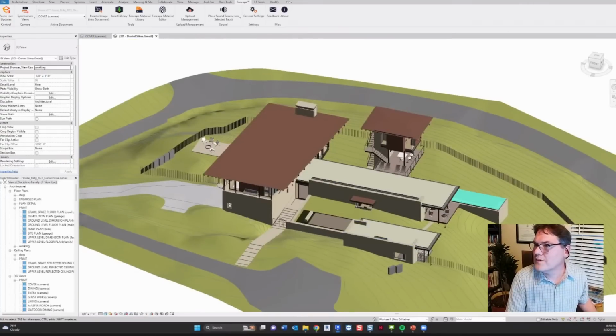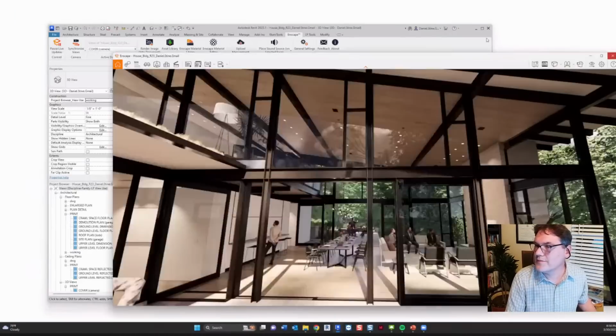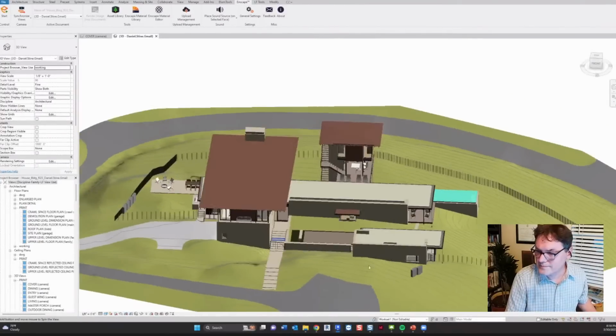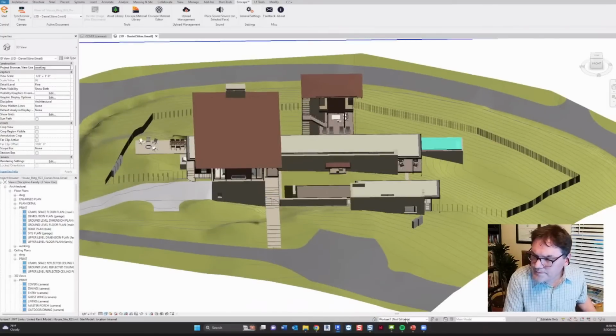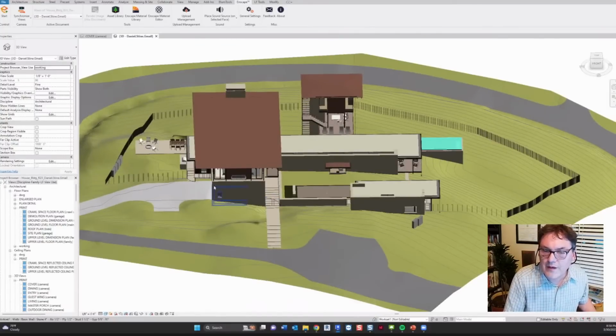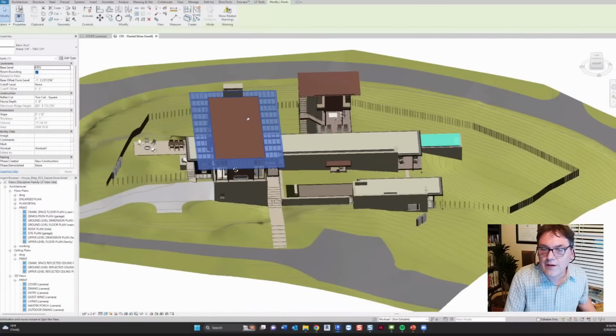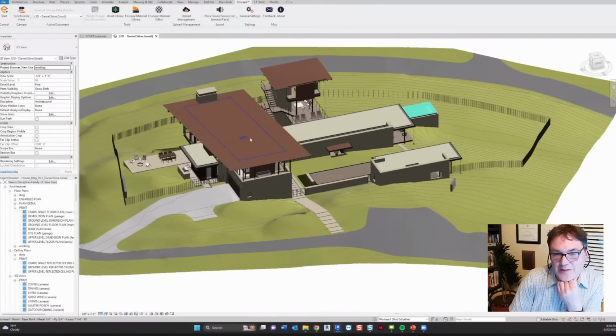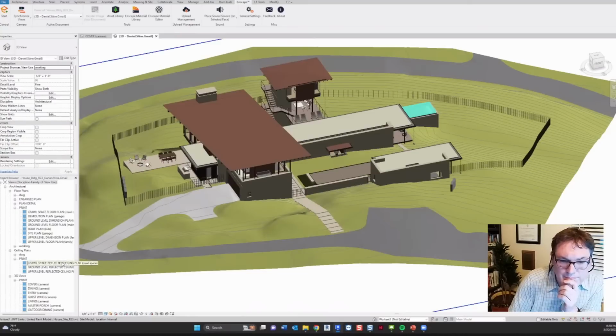So in this particular scene, I don't see design options on the bottom hiding. Are you just using the category to hide entourage in this one? In this case, it's all in the site model. So right now the site model's not showing up, so it's linked. The entourage is actually in a linked site model. Got it. That's another way too. I guess I never thought about that.